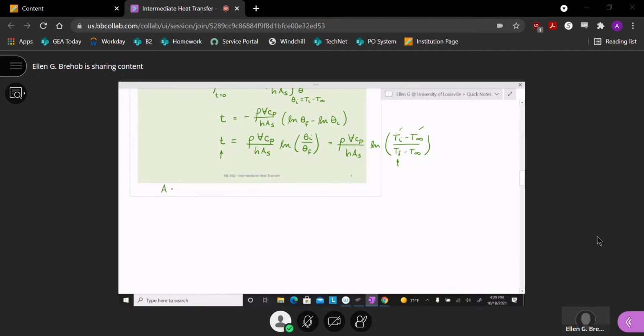You know, I should be listing some assumptions. Okay, so we're no longer looking at steady state, so we know it's transient. And the other thing, a lot of times we'll say one-dimensional conduction. Well, we're not assuming that either. This is really zero-dimensional conduction, as long as it behaves as lumped capacitance. We do need to check that. We are assuming constant properties. I'm going to add explicitly that h is a constant, and that heat storage is sensible heat storage.